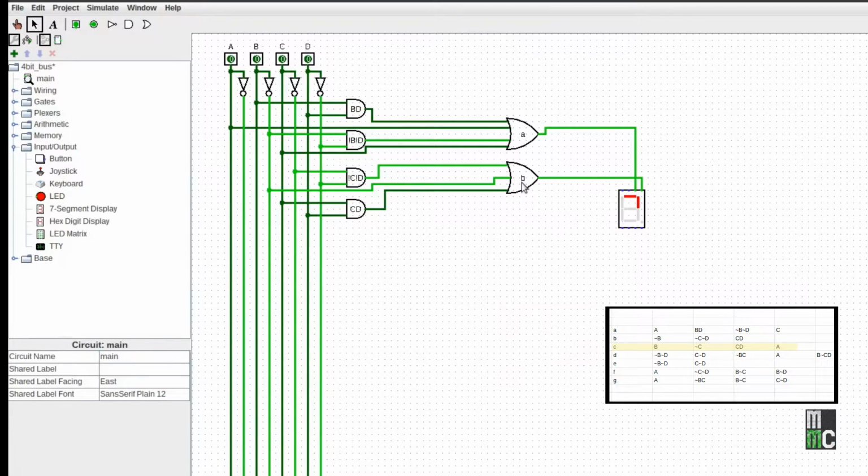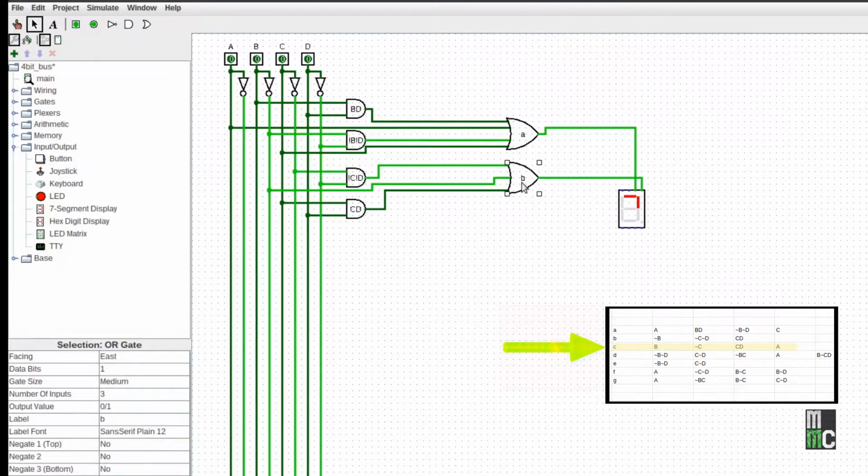Okay, moving on to the C gate. The C gate, as you can see, has 4 different inputs, so I'm going to copy this. It's got most of what we need. I'm going to put it down here. Relabel it as the C segment. Hook it up to the C, which is this one right here. Keep in mind that is the point, and we're not using the point. So now the conditions that we have for the C gate are B, A, not C, and C, D. Those are what we need for C gate.